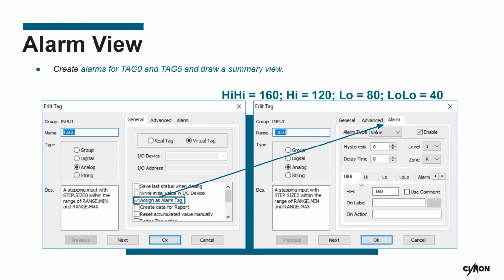High and low are generally safe thresholds that you can pass. It's kind of like a warning. And then high-high and low-low are your extreme alerts. Like, hey, you've passed a pretty strenuous threshold. We need to alert you and you need to act now. It's an extreme notification that requires intervention. Whereas high and low are just warnings, like, hey, you passed the threshold, maybe monitor it, but then it'll probably come back down and go back into a friendlier steady state, or back to equilibrium inside your project.